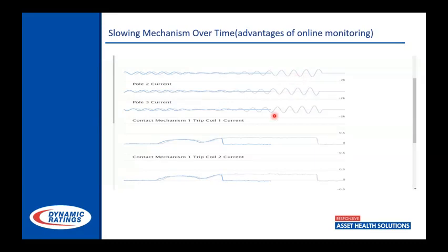So just looking at this and thinking it through, it really looks like this breaker's not coming open. The contacts aren't parting as far as they should part when the operation's initiated. So thinking it through, it seems like it would probably be a latching issue to me.